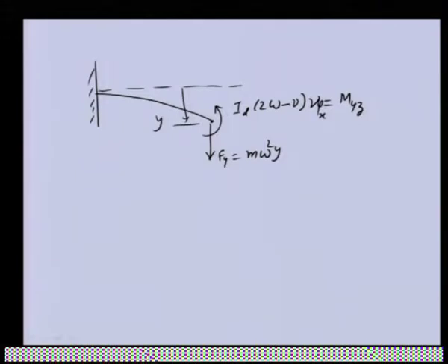So now apart from this, we have this angle. If we project the tangent at the free end of the shaft, this is the phi x. So that means we need to relate basically this linear displacement or translatory displacement with the force and influence coefficients which we defined earlier, alpha 1 2, and similarly angular displacement will be given by this force with influence coefficients.